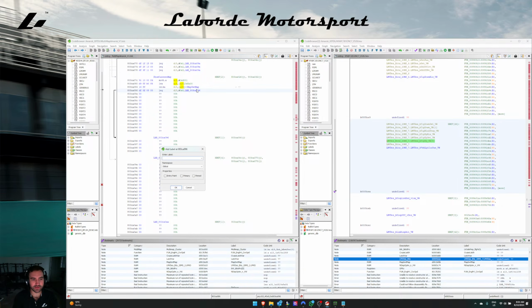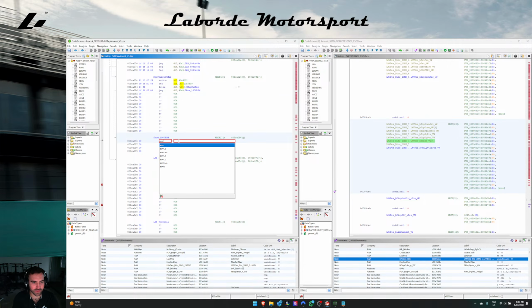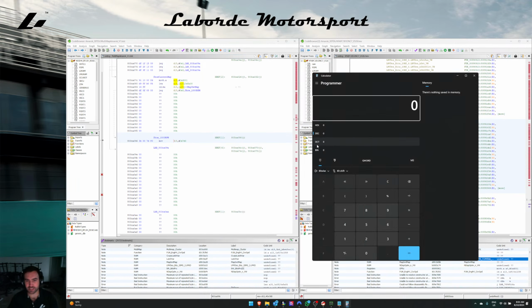So this is going to be show 1000 RPM. Okay, then we're going to move the value of 1000 RPM into data register 15. Usually it'll be like 7D0, something like that. If I go to calculate, this is just my experience, right? 7D0 is 2000 in decimal, but that's usually what 1000 RPM is. And then to find out what 2000 RPM is, we just times it by that, and then it's FA0.